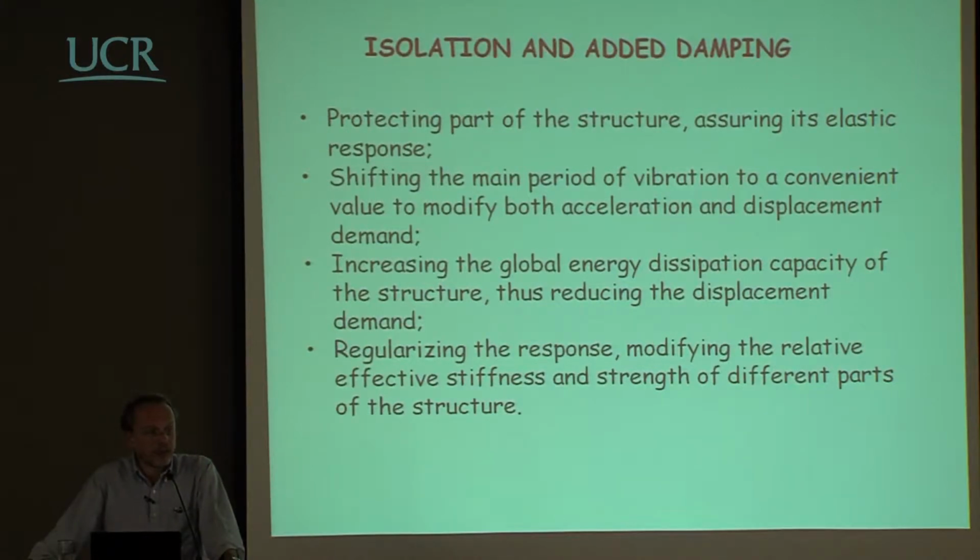And I will try to discuss this point conceptually with reference to the examples that Nigel presented in the previous lecture, just to show that it is possible in principle to design some sort of isolation system for a bridge in such a way that the response becomes very regular, and therefore everything is much easier, not only from the point of view of calculating the structure, but from the point of view of the response of the structure, which becomes more acceptable because there are no concentrations of demand in one pier or in another one.